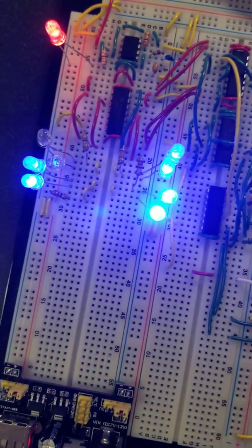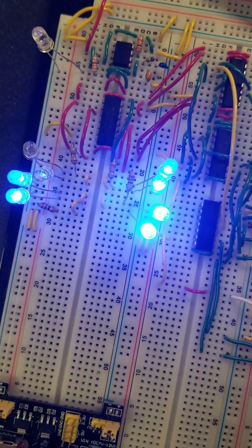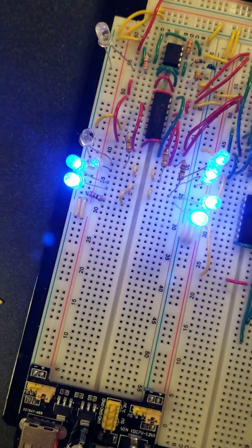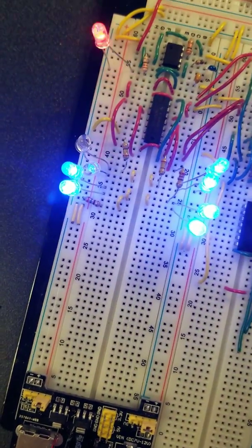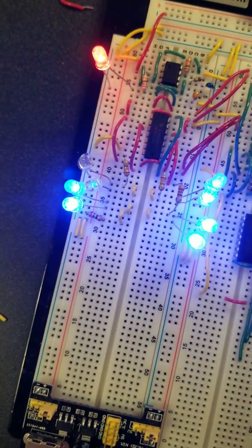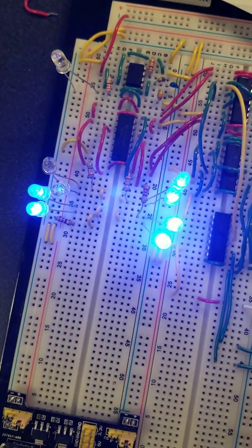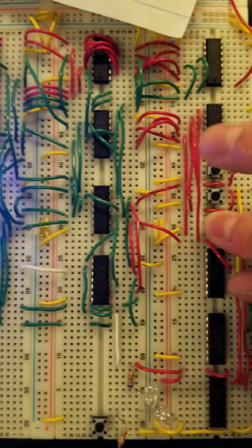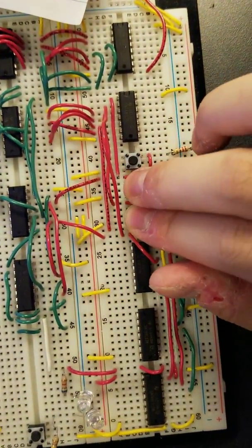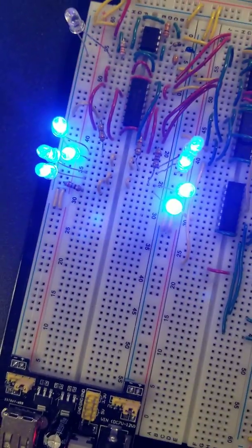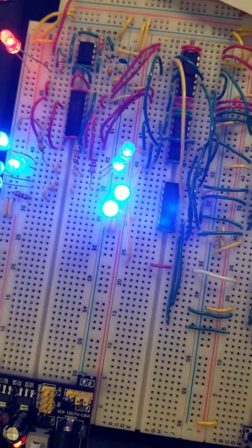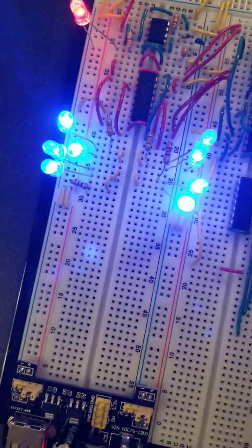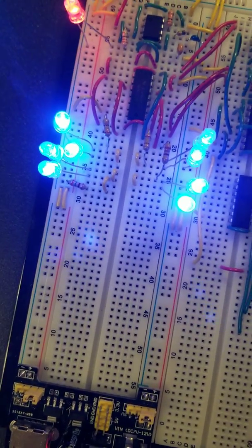And as you can see, the power on the left has dropped by half, while the power on the right stays the same, simulating the fact that the tracker will move on more of a right curve. And now when we get back on the line, that's when P34 is a 0. So when you press the button, everything's back in the straight state.